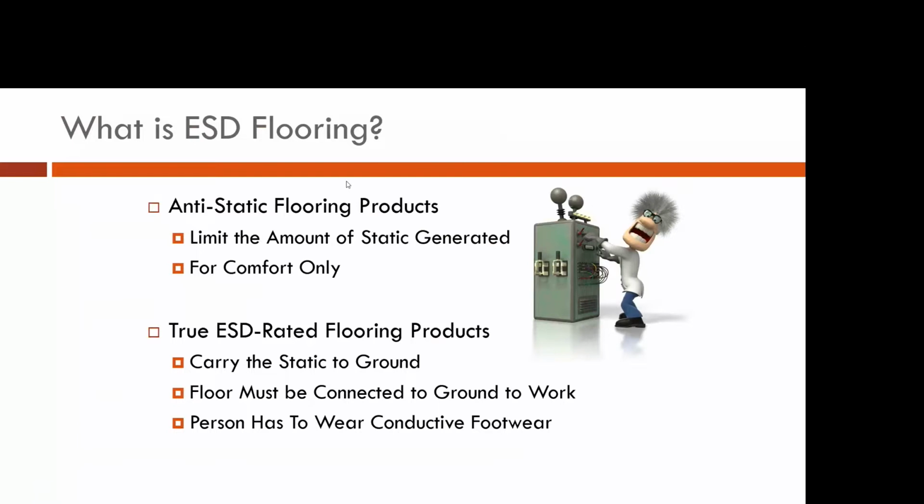And with flooring, ESD flooring begins as anti-static flooring. So all ESD flooring should be anti-static. It should limit the amount of static electricity generated when walking on it. So true rated ESD flooring will generate less than 100 volts. And anti-static flooring stops there. It's not grounded. So it doesn't remove the charge off the body. It really is only reducing the amount of triboelectric charge built up when walking across it.